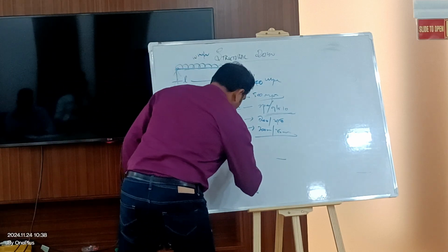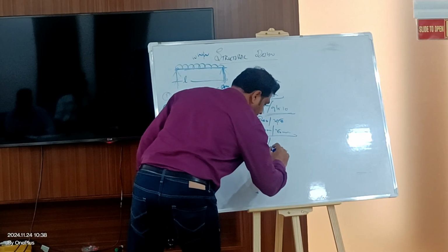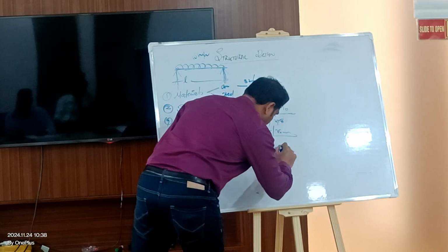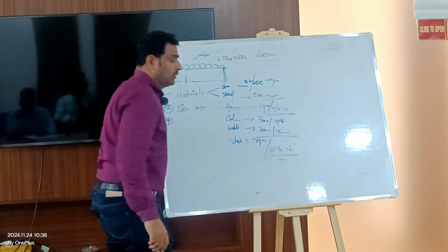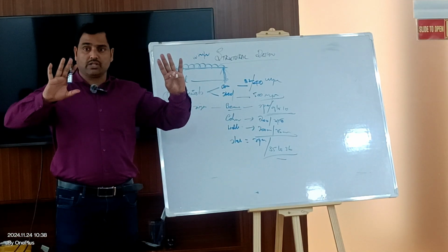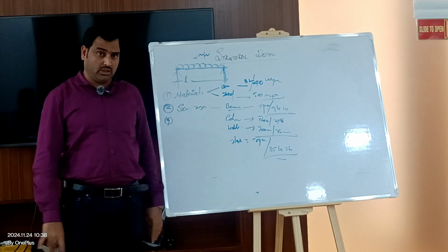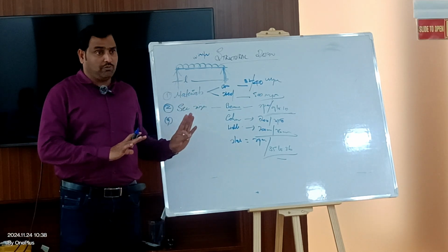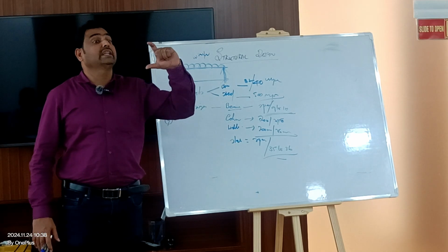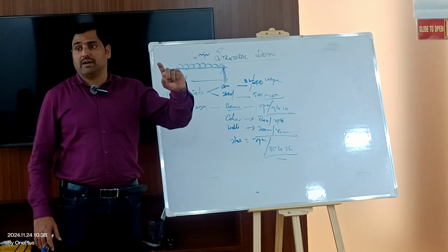Going with slabs, span by 35 to 36, more practical, because we are going to design the live project. Span by 35 to 36 defines the overall thickness of the slab. It doesn't matter actually.